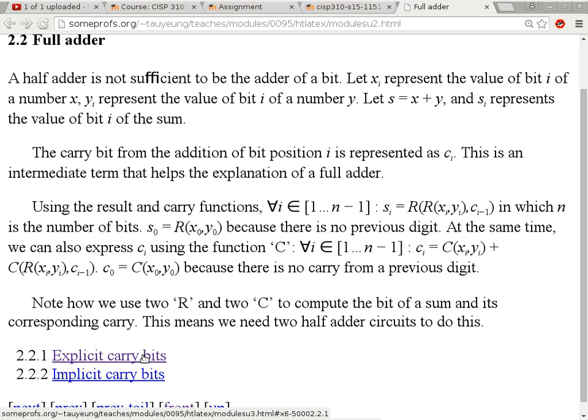So Intel, instead of just tossing it and saying, oh, this is kind of defective because it doesn't operate at what we want, would still sell it to you at a lower price and say, this is a good chip. It just needs a slower clock. Yeah, a great 2.3 chip. And it's done a lot with semiconductors. After manufacturing, after you actually get the chip or the die, they would then characterize and sell the chip according to the grade that it is characterized at.